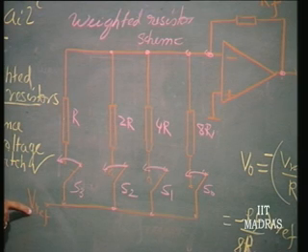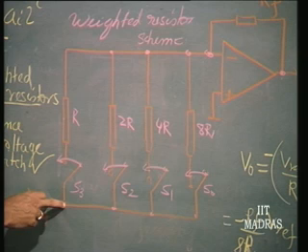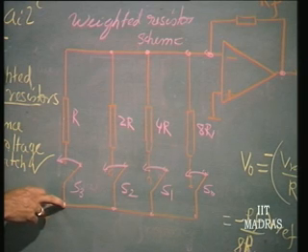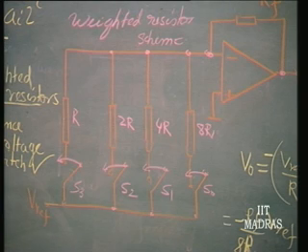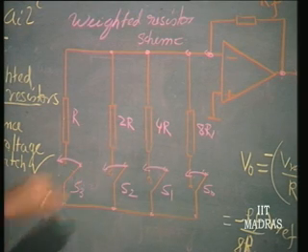Therefore, if this is not an ideal source, if it has a source resistance here, this voltage itself will change, right. So, that will appear as a noise, which will be purely dependent upon the switch position. Have you understood this? So, this voltage will change in a very random fashion depending upon the switch position. So, that causes an error in this.